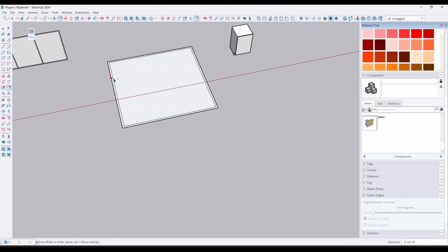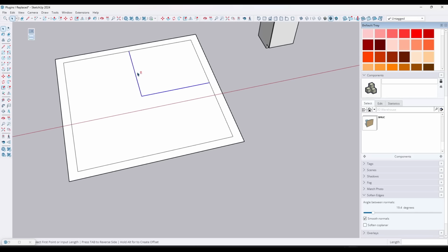Now this could be especially powerful if you wanted to do something like creating walls from edges. So say I was to offset these in like this, but say that I had a wall and I wanted to draw it like this, I could use S4U offset to offset those edges in two different directions like this. So if I wanted this to be a 4-inch wall, for example, I could just type in 2, hit the enter key, and that's going to offset this in both directions.